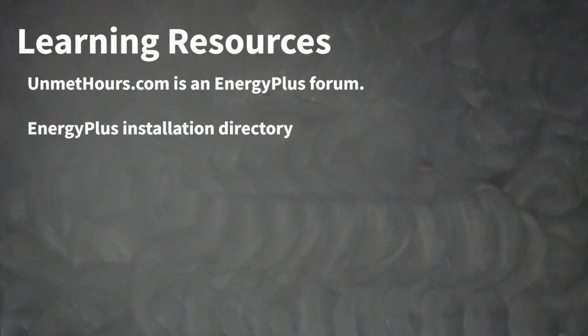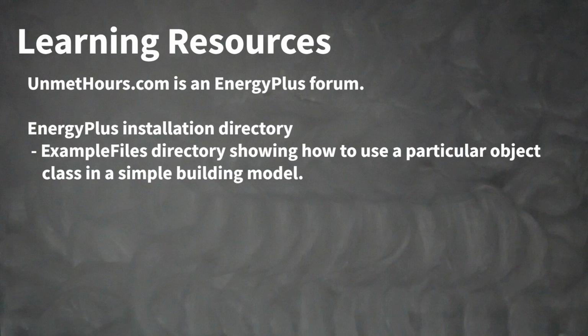There are some resources in the EnergyPlus installation directory. The first one is the example files directory, and that's no space in between example and files. In that directory, you have a bunch of IDF building models, and usually they'll show you how to use a particular object class in a simple building model. So you can study that and then figure out how to take that particular object you want to put in your model, and you at least have a template or an example to work with.